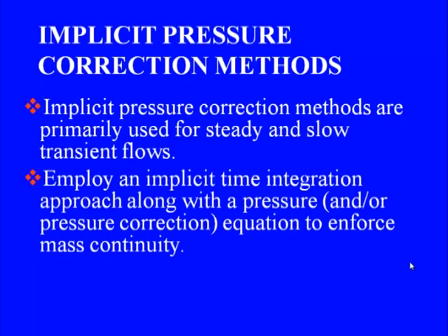And we will employ an implicit time integration, unlike explicit time integration techniques, along with a pressure and or a pressure correction equation to enforce mass continuity. We will first discuss a scheme which bases the corrections on the pressure equation, and then we will take up the SIMPLE algorithm, which is based on a pressure correction to enforce the continuity equation, and the SIMPLER algorithm, which would involve both pressure and pressure correction solution.